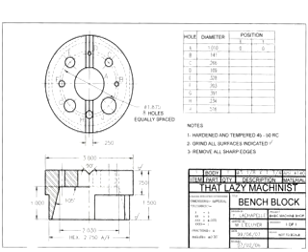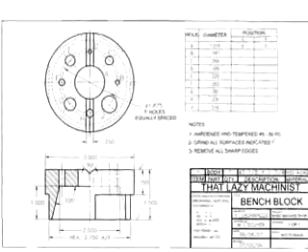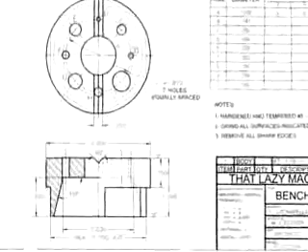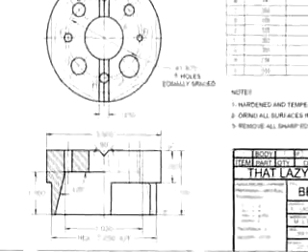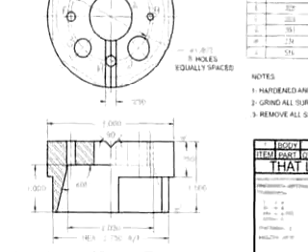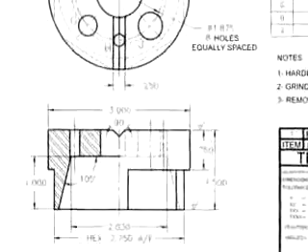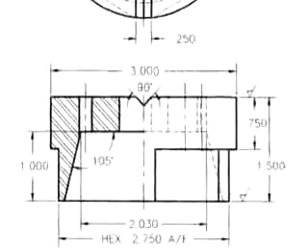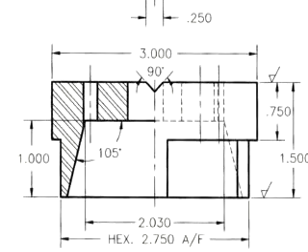One of the reasons for using section views is to eliminate clutter. It's kind of like not seeing the forest because all the trees are in the way. Hidden lines and contour lines are important parts of a drawing, but sometimes there are so many of them that they confuse things. If we create a section, we eliminate a lot of them, because obviously whatever is in front of the section isn't there anymore, and that's contour lines. And as a general rule, we do not show hidden lines that are behind a section view.